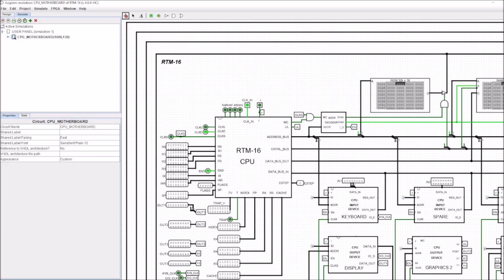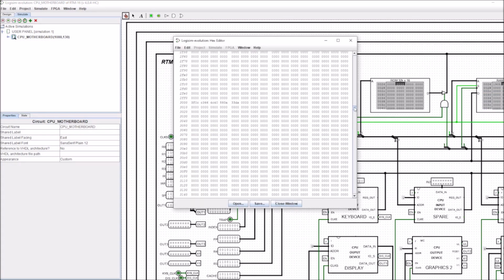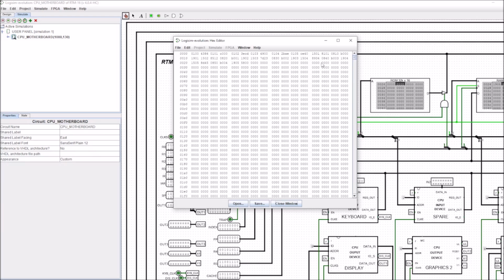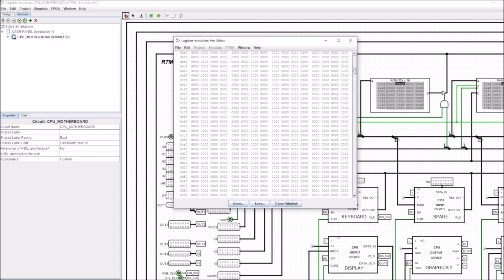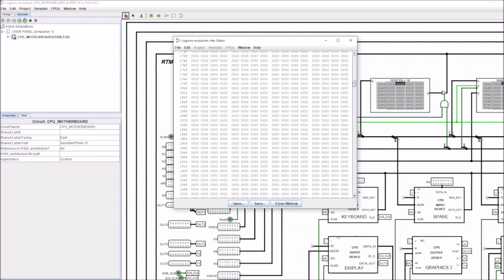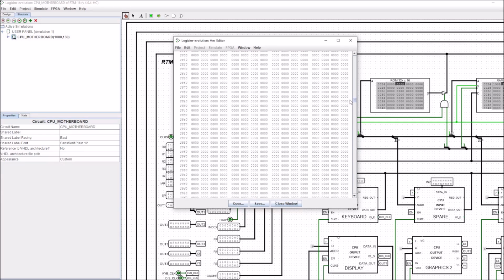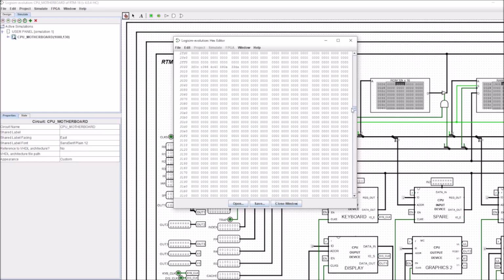So if we drop down into the RAM, now the result is at 0B00, but remember this actually starts at 8000. Okay, although it says 0000, it's actually 8000 because the ROM takes up 32K and the RAM takes up the other 32K, so they're split. So if we come up here, it should be 3000. So 1, 2, 3000. Okay, so there are the answers here.